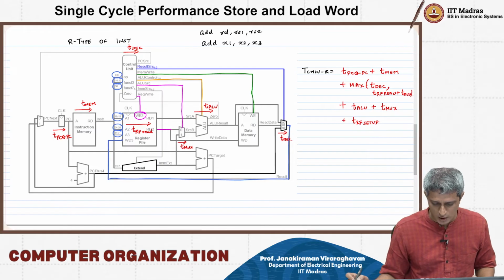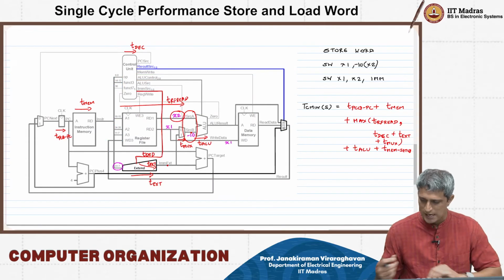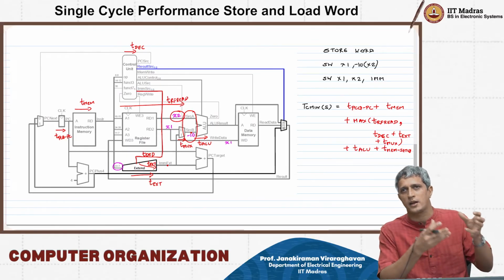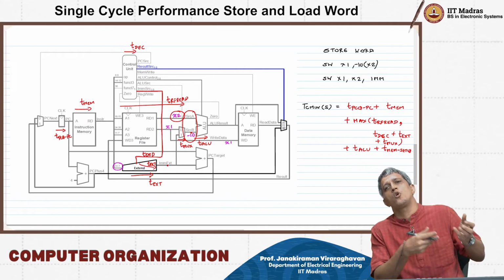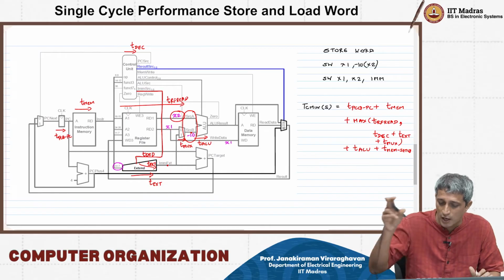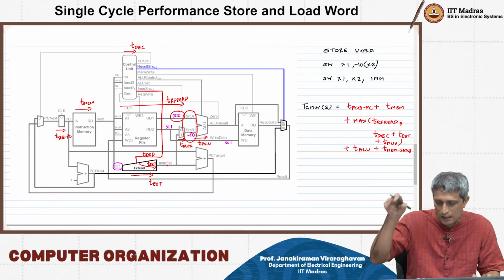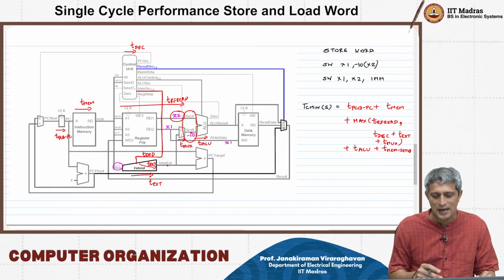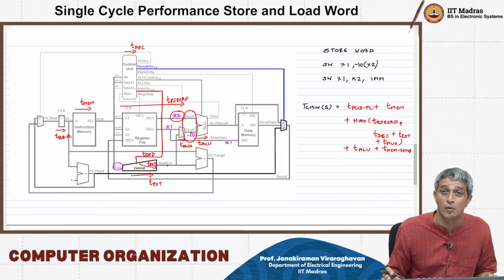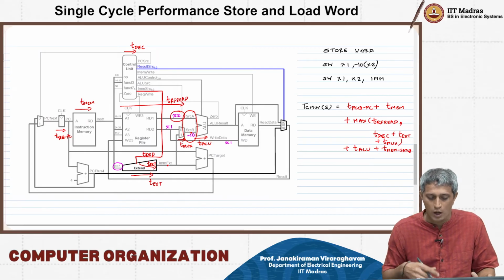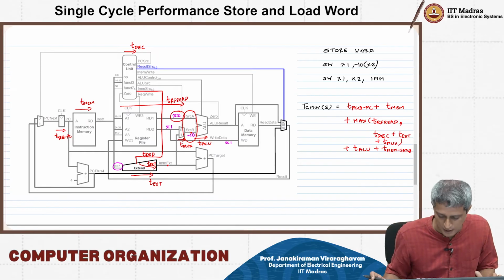We were talking here of T decode, right? But the key idea is that you do exactly a similar thing. You take read two registers out, you're going to compare it in the ALU, and then the 0 signal is going to get set, it goes back as an input to the control unit, and then that is going to determine your PC source, whether you are doing PC plus 4 or PC plus some immediate data effectively.